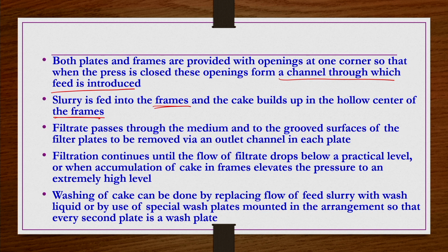or by use of special wash plates mounted in the arrangement, so that every second plate is a wash plate. Remember this, of the two plates, one is the filter plate and another one is the wash plate. During the filtration process, both the filter plate as well as the wash plate act as filtration medium, so that the filtration takes place. But in the case of washing, only the wash plate acts as filter medium, and the feed plate is not going to act as a wash medium.